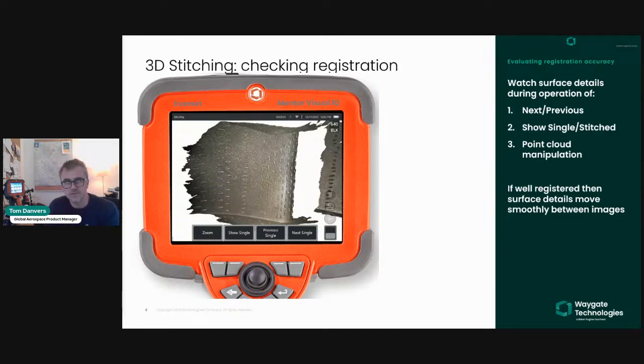So you can capture many more than 5 images, but you can only actually stitch 5 images as a maximum together. So if you choose to discard some of the images that you captured, that's fine, in order to reposition the probe or reposition the component in relation to the probe, and stitch again and reattempt the stitch, to make sure that you've got a good quality match between all of the individual images together.